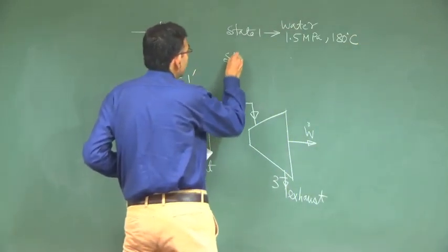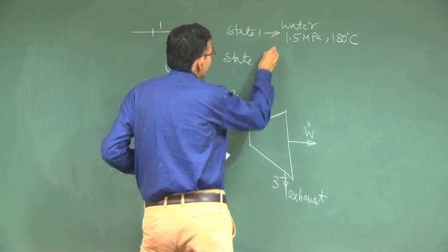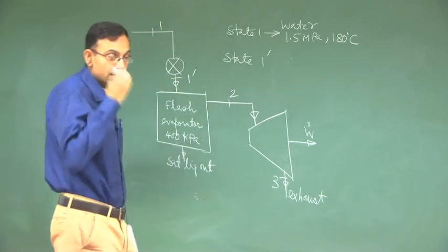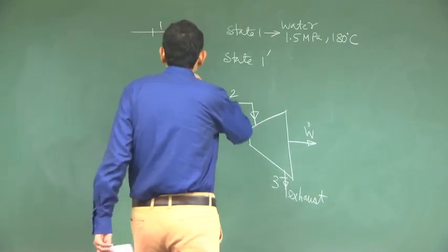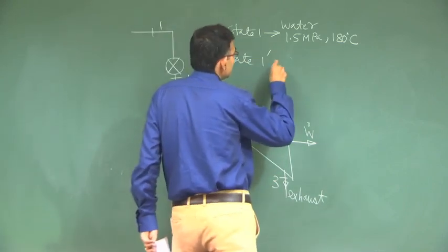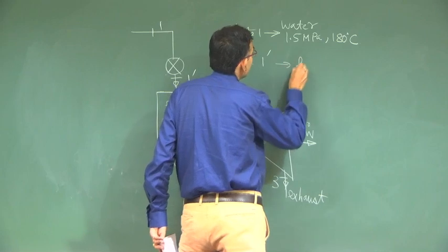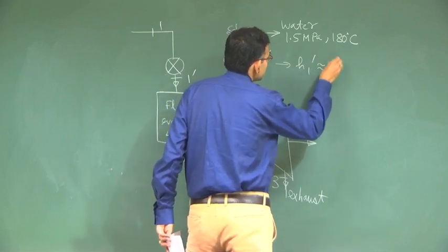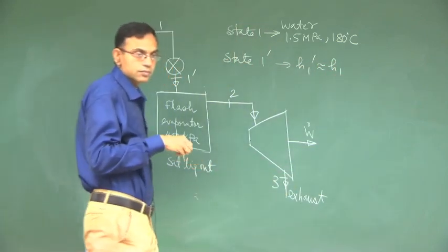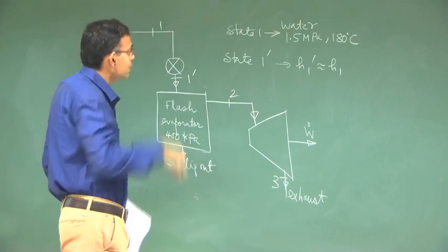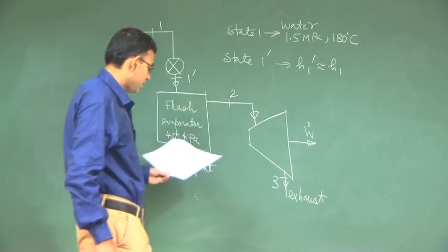State 1 prime, what is it? We have learned the throttling process. Across the throttle valve you have negligible change in enthalpy. So, H1 prime is equal to H1.